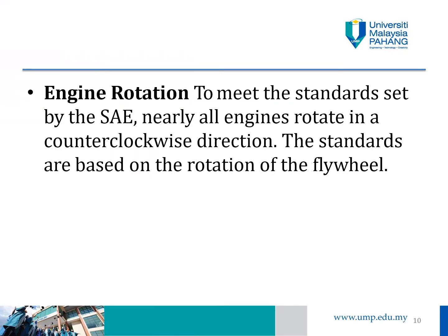So engine rotation, okay, to meet the SAE standards, nearly all the engines rotate in a counterclockwise direction. Okay, so this is important because later on when people want to design the flywheels and the gear mechanism, they have to use the counterclockwise direction to make their design.